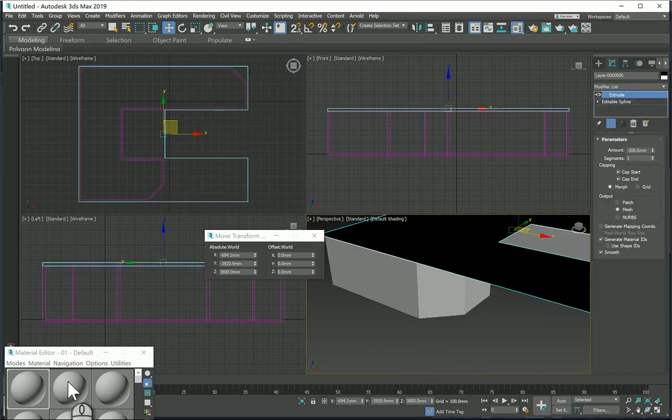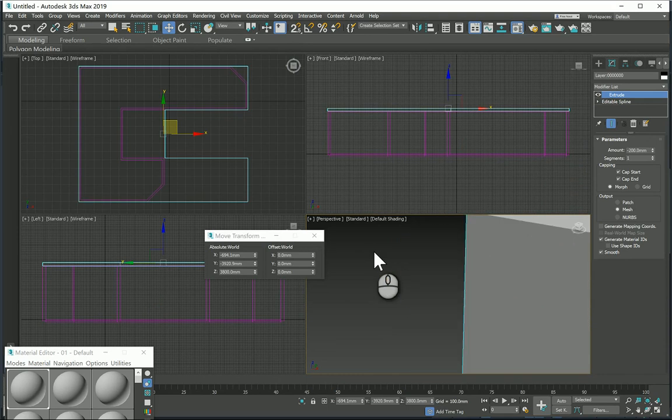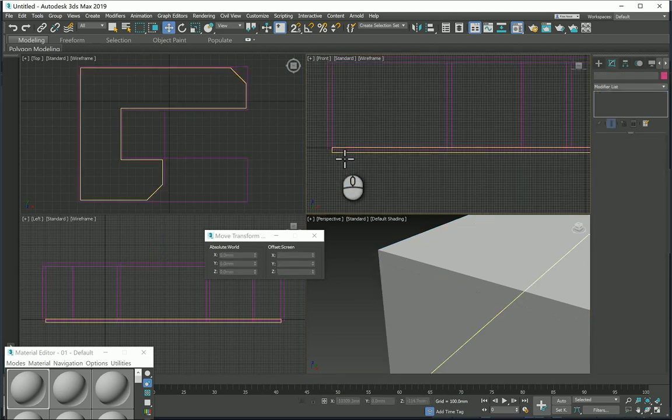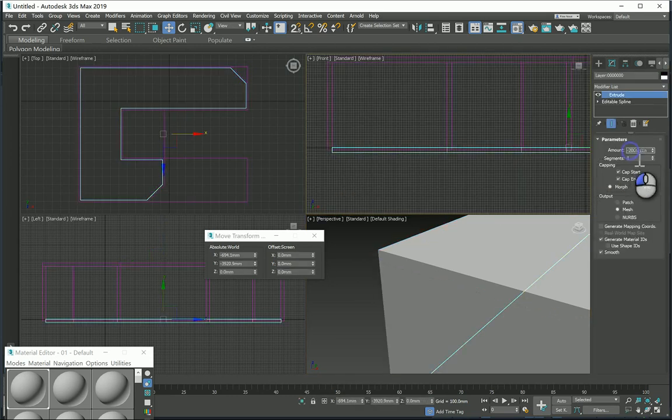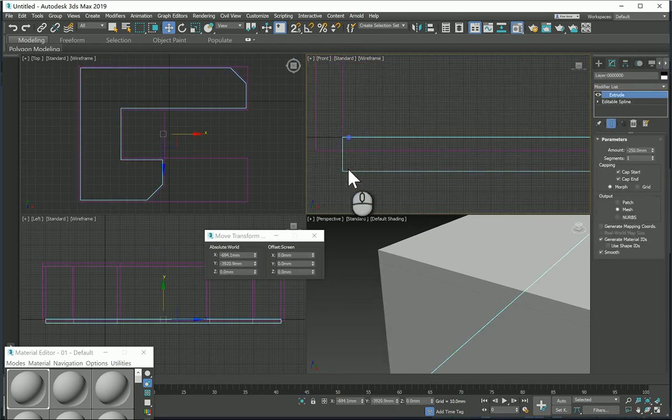I'm gonna drop a material on it, and there will be a gap, of course, because the lower one was only 250, and sorry, only 200. Now I'm gonna make it 250, and even this one, to be honest, just to be consistent with those, I'll make them 250. So you see, when you make it 250, it won't affect anything because it's pushed downward. That's the super other benefit of keeping it at the AutoCAD level, and always the extrude is a minus thing.